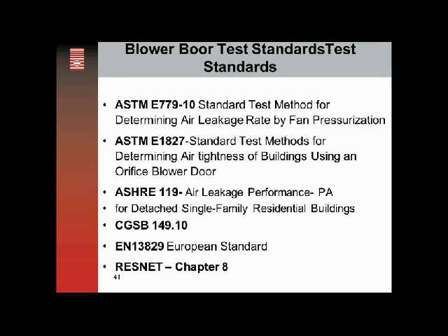And again, the one that I think people really need to keep their eye on, HERS raters should already be familiar with this test standard, but if you're not, get a copy of the ResNet standard and become familiar with one of their 3 testing options: the ResNet single point test, the ResNet repeated single point test, or the ResNet multi-point test.